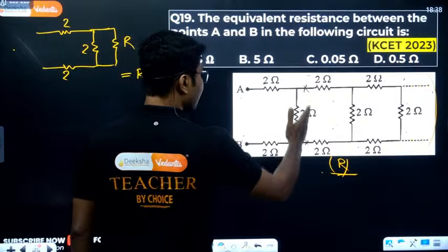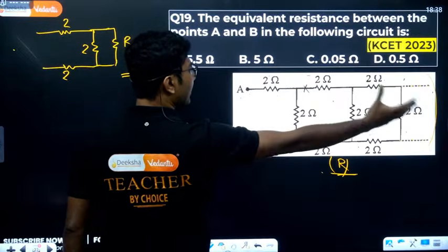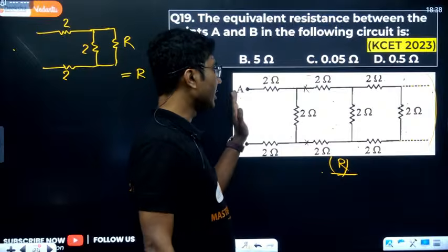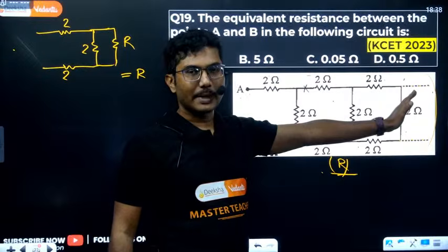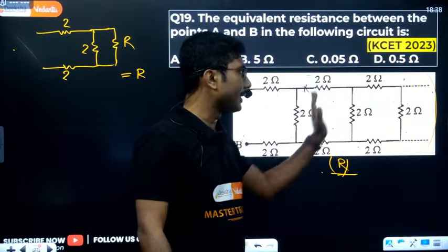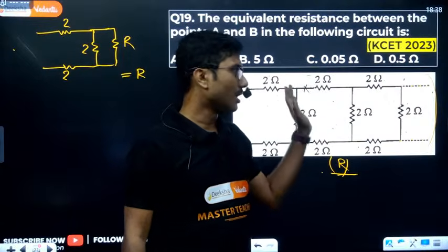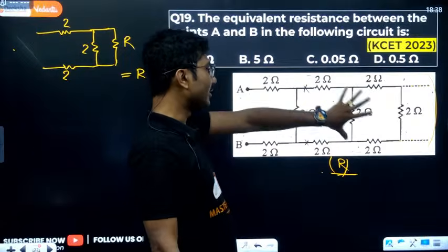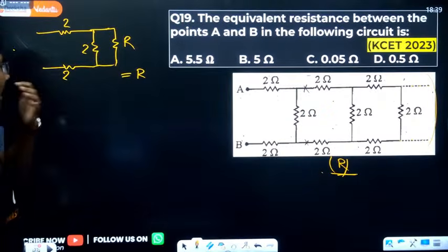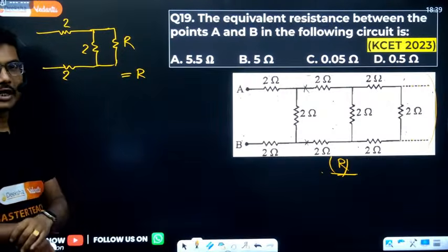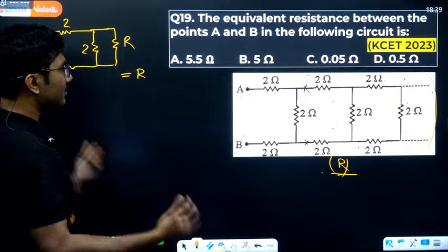Find the symmetry point, which pattern is repeating again and again, take the minimum portion of it, cut it out, and say that this is the pattern which is repeating. So the total resistance of the circuit is R. The repeating pattern should also have the resistance R, because it's an infinite circuit, then only it is possible. And then you add that R over here and say that this combination will also have a resistance R. Now we have to simplify it and solve it.